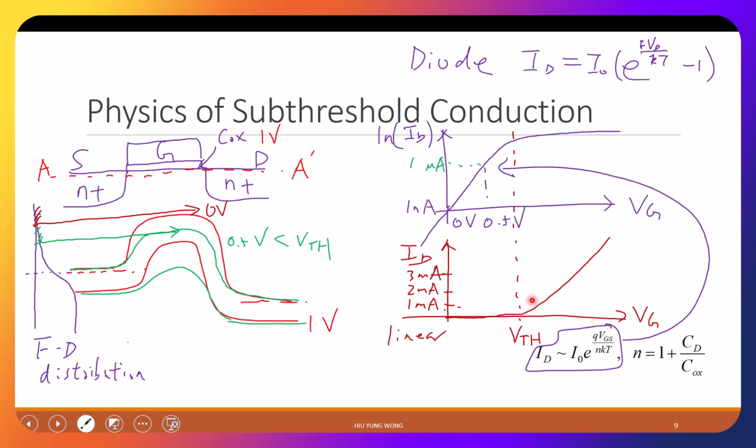Your diode does that, so that's very good. You also see something like this in a diode, right? In linear scale, usually they say turn on voltage of diode. But if you plot in log scale, it is not abrupt. It goes up smoothly. Okay?